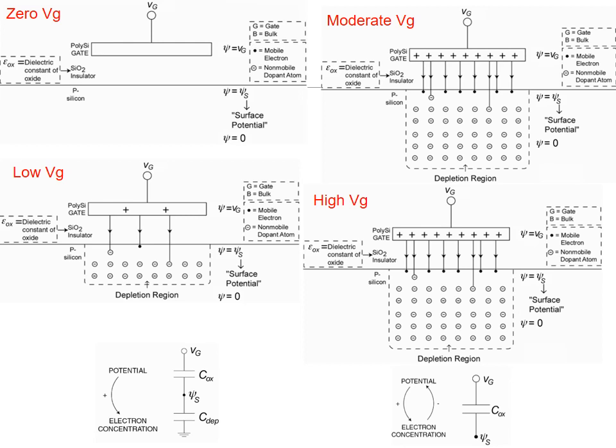This is a picture here depicting essentially the reason for the subthreshold coefficient due to the depletion region in the subthreshold region. But then what's interesting is that in above threshold, we effectively don't get this behavior anymore because the surface potential gets pinned to a certain value when it's saturated with excess electrons in the depletion region, and conduction from source to drain becomes a lot easier in this condition. So again, if you want to learn a little bit more about this, the Sarpeshkar text is a very, very interesting read if you want to explore a little bit more.